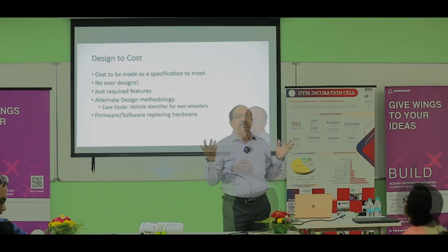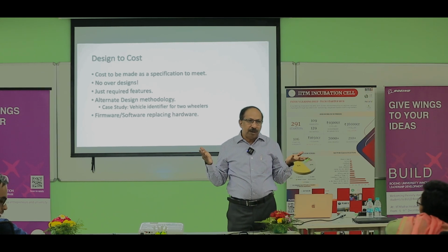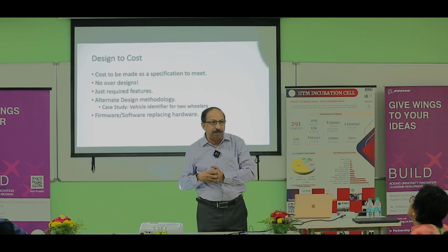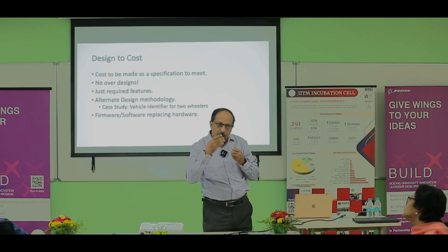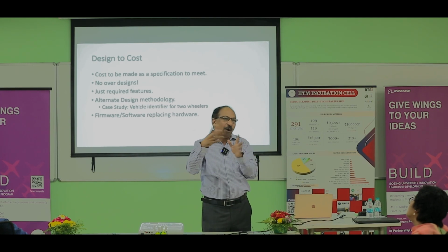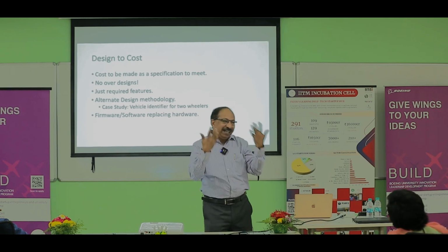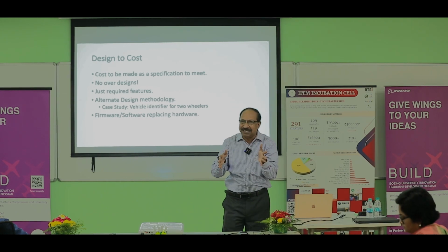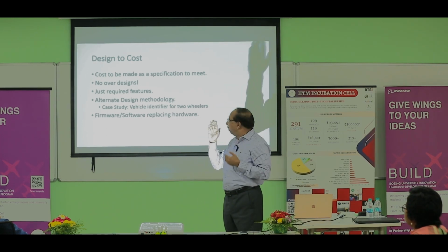But here the requirement was that the price can be as high as 1,000 rupees. After that, nobody is going to buy. When we did the design, the bill of material cost itself was coming to 1,200 rupees or something like that. Then what we did was remove the chip solution. We came up with an oscillator using a transistor and a coil of our own. Then only could you meet that product cost. So you have to think in that way also. It is not always that a ready-made solution is available. Of course, the risk is less that way. You will pass through the compliance test and all, but you have to be very careful.